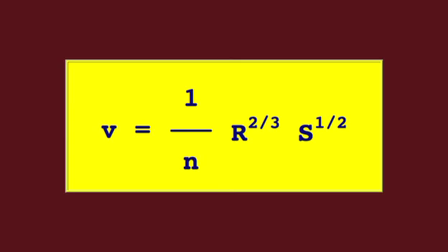Design velocities for vegetated channels do not exceed maximum permissible velocities. Design velocities are calculated with the Manning equation. Design tractive stresses should not exceed the critical tractive stresses. Design tractive stresses are calculated with the bottom shear stress equation.